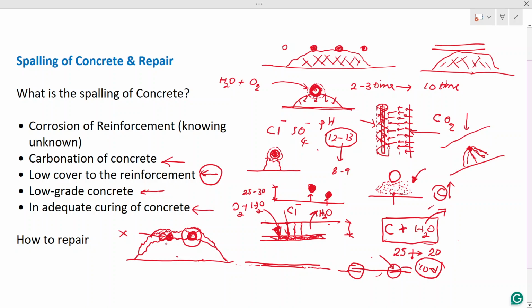Right, now your reinforcement replacement and cleaning is done. I forgot to tell you, when you clean the reinforcement, you have to clean it extensively. Otherwise, if you leave it rough, there will be debonding. Once you clean the reinforcement, you can apply anti-corrosive to it, which will avoid further corrosion. But before applying anti-corrosive, you have to make sure 100% cleaning is done. Now your strengthening process is almost complete.